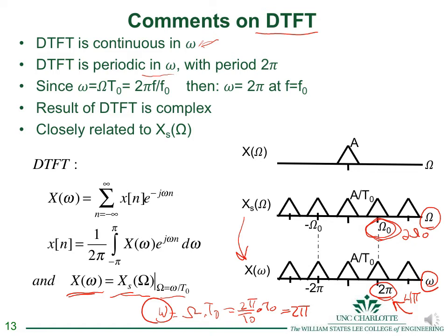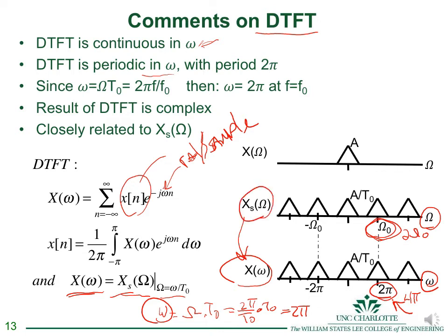And so the discrete time Fourier transform is computed directly, again, from the data that comes out of the A to D converter, the x of n, the discrete values. And it's computed directly using the discrete time frequency in radians per sample. And so, again, this is radians per second for the Fourier transform of that sampled signal. Again, that's the sample comprised of the impulses and so forth.